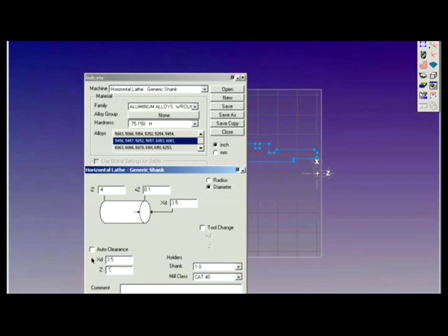This user-defined clearance sets a fixed set point for all moves to clear to. The difference is that auto clearance is more efficient because the system looks at the stock and the part and clears it automatically, avoiding any feeding in air or unnecessary motions.